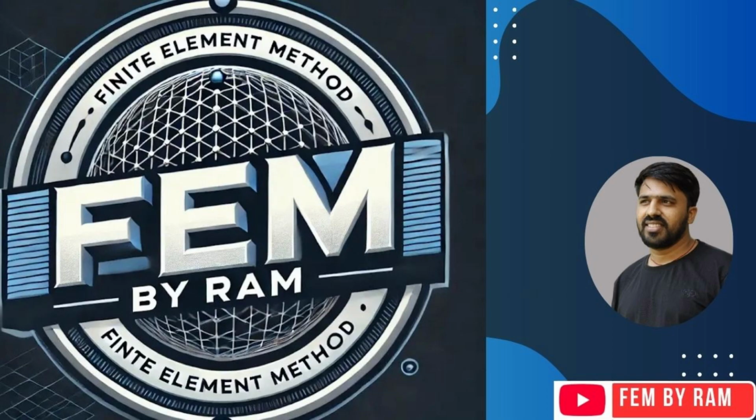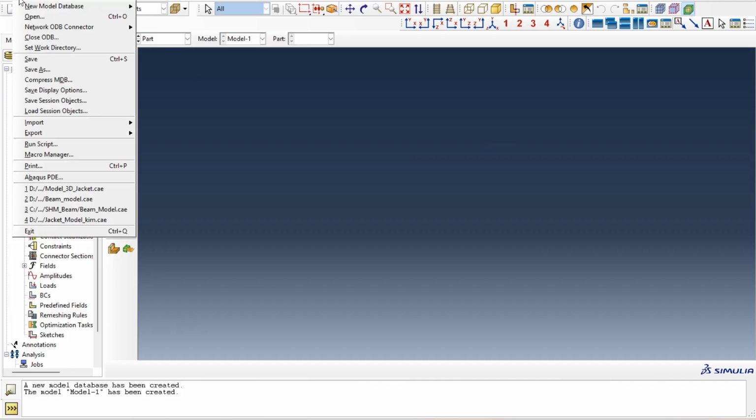In this video, we are going to learn how we can model a beam element in ABAQUS software. First step, we have to set our work directory, because normally when we are working, we forget to set it. For example, if I forget to save my work directory and come back after 1 hour, I will not be able to find where my model is. By default, if you forget to set your work directory, it will go to a temp file. So first we have to set our work directory.